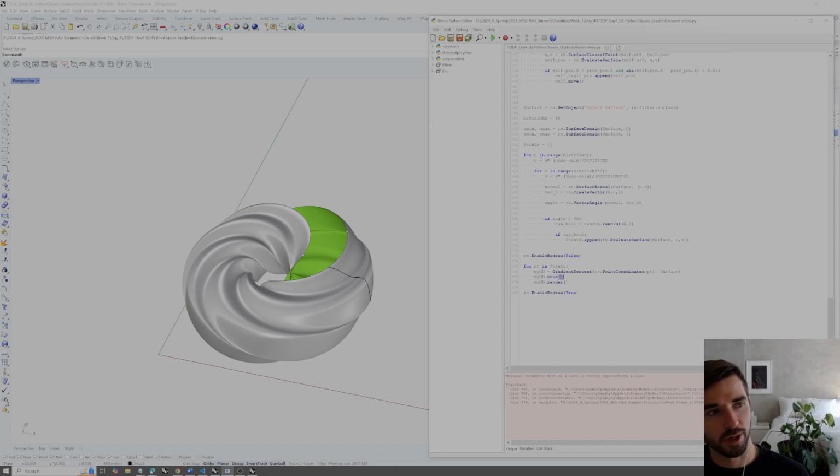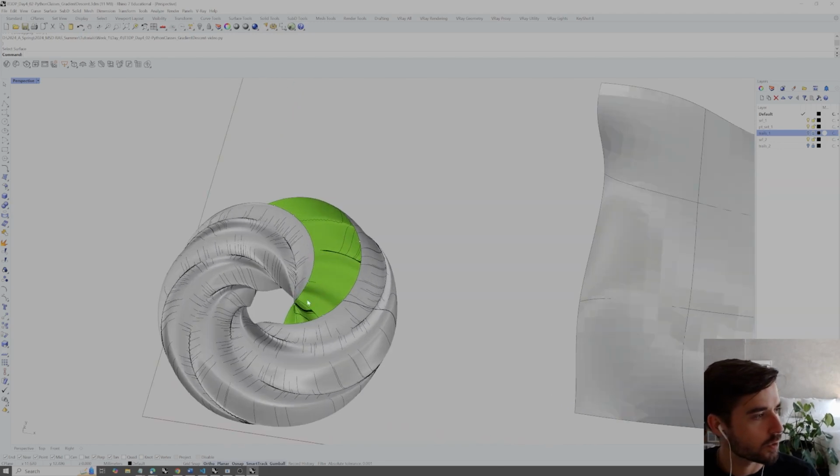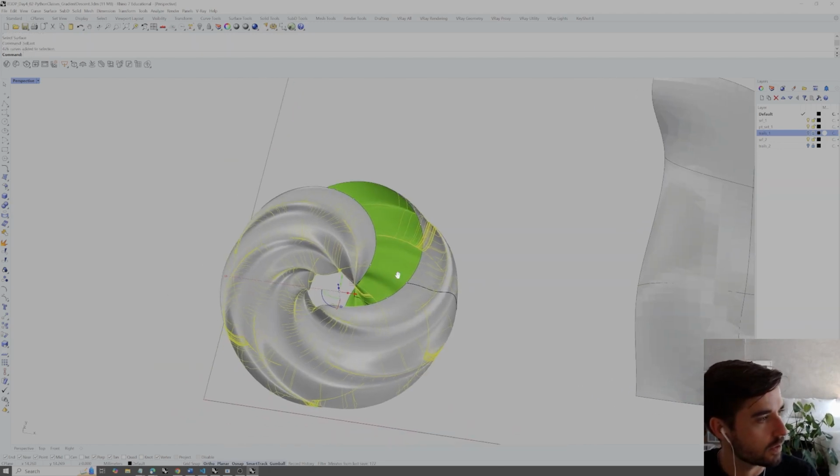And now we are getting one issue here because we do need to adapt this for feeding in our point values. Why is this? Because we get an output of an X, Y, and Z value from our surface, and we're appending those, not a GUID, to our points list. That's actually great because we can just delete our point coordinates, and we can directly feed in for point, which is an X, Y, and Z point, in points. So we don't even need the point coordinates anymore. Now if we click play, select our surface, we wait a moment, and then our trails will be drawn out on our surface. So now we see all of those trails being drawn across our surface.